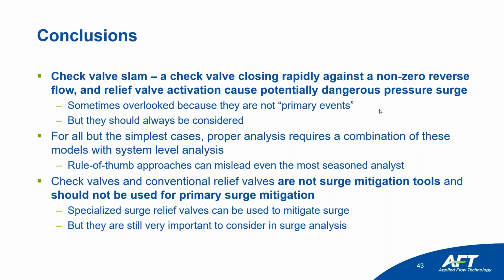And obviously related to pressure is force. So you can have this radial force that might serve to burst a pipe or damage equipment from the inside. But you can also have what I would call a transient longitudinal force on something like an expansion loop. That's a very common configuration in the system, and in the types of events that we're talking about in this presentation and these papers, you can easily see that force exceed 50,000 pounds or something higher than that. It's not outside the realm of possibility. So that's the reason, to protect the system.